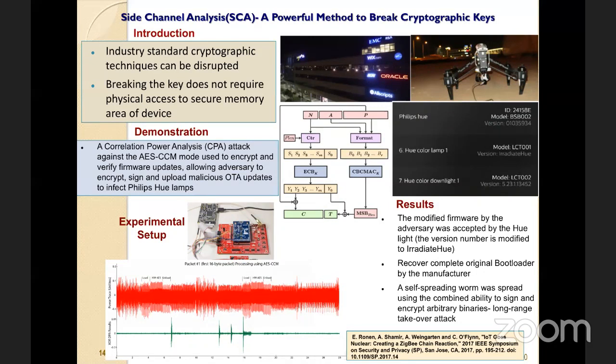So what the attackers first wanted to see is whether they could update the firmware so that this proximity check is removed. You can write the firmware, because it is on a standard processor, but you cannot make the firmware run on this hardware, simply because there is an authentication check, or a MAC check, which is done by this system.